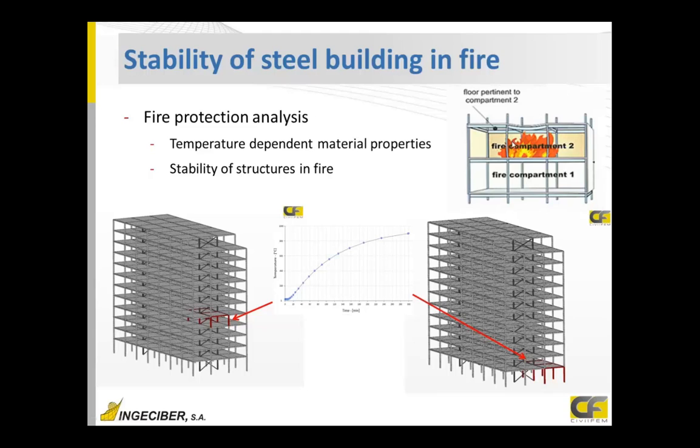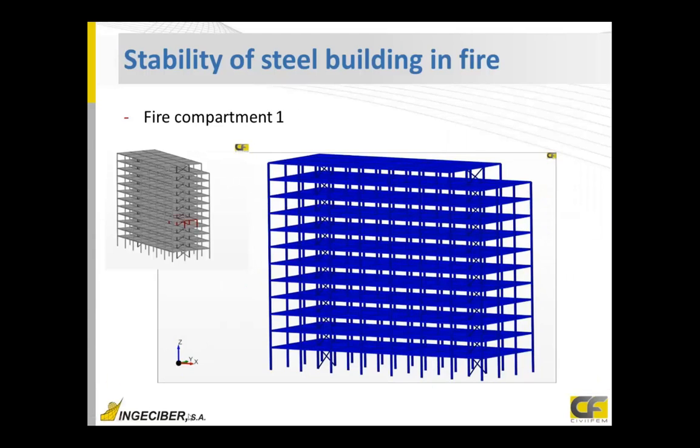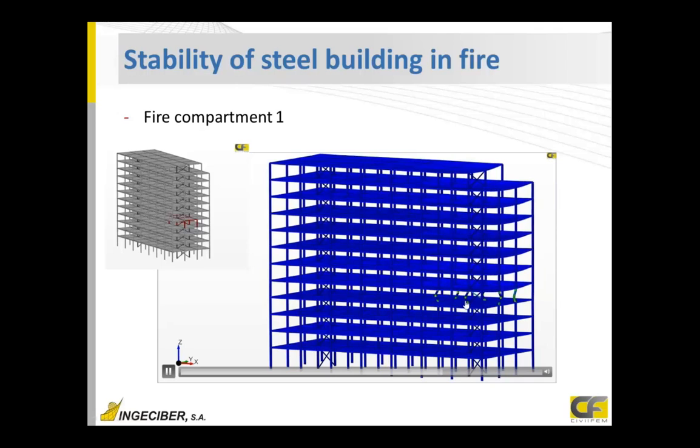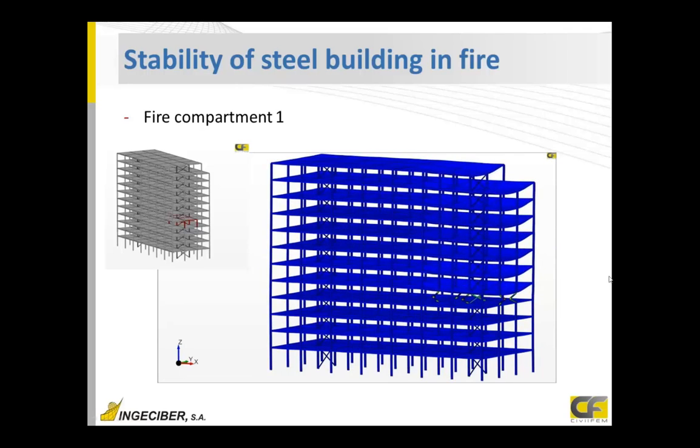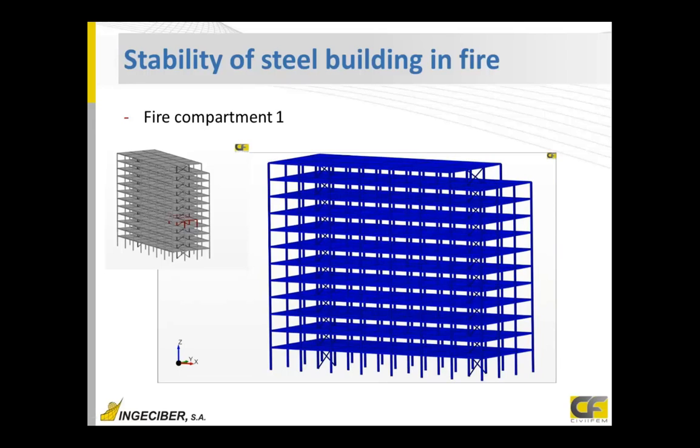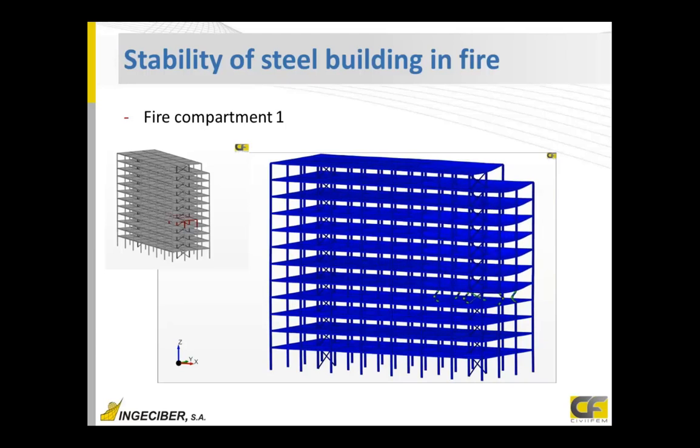We do it in different fire compartments to analyze possible fires that we could have and whether they can generate instability and time for collapse. So we apply these loads first to a possible fire in this zone and then a possible fire in this other. For the first zone, we can see that after some minutes, buckling starts happening, because in CivilFEM's thermal structural coupled analysis, material properties are time-dependent, that is, temperature-dependent.